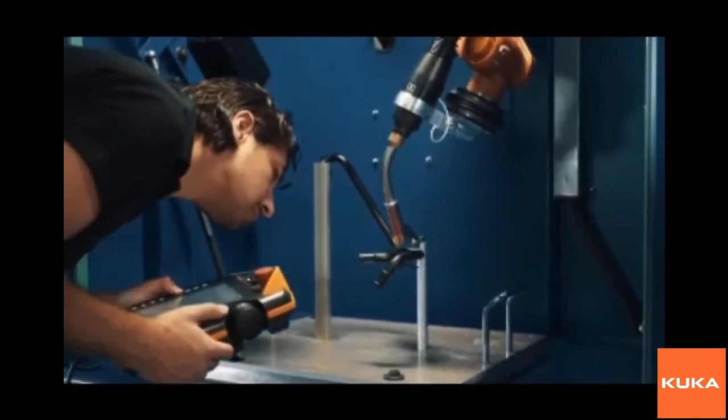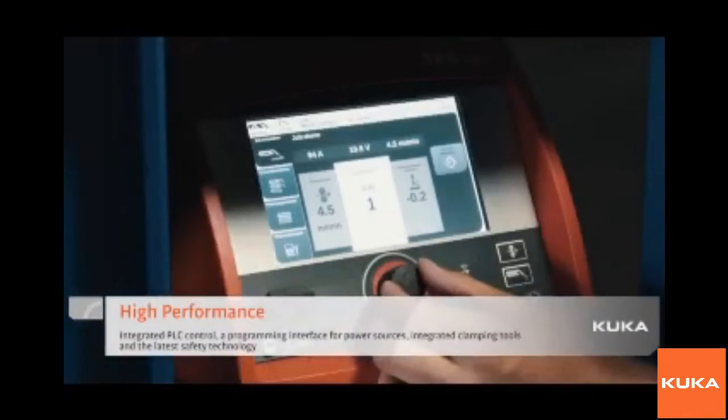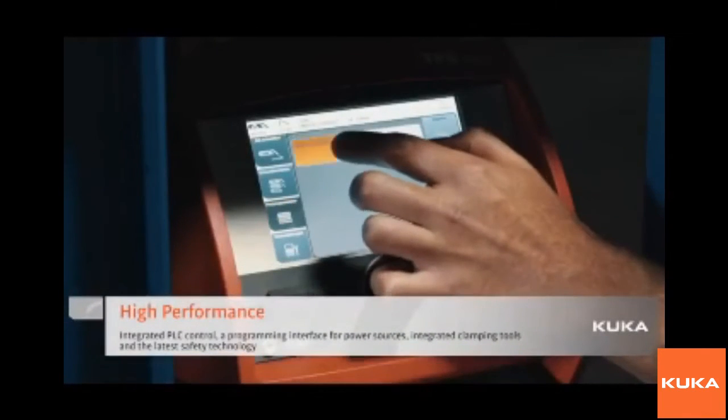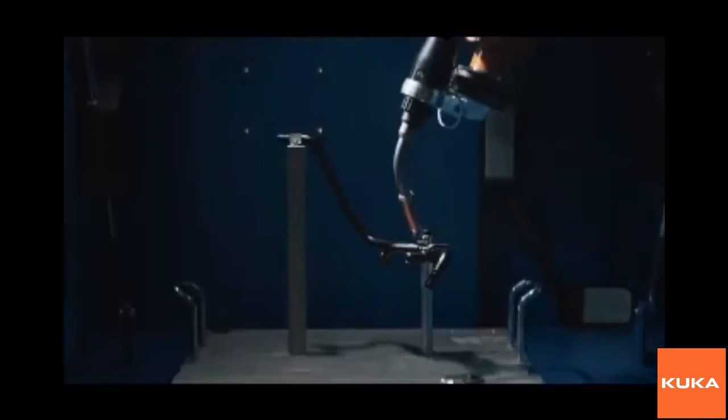You can see here the programmer is moving the robot. This is how he is teaching, and now you can see he is teaching with a 6-dimensional mouse. It is very easy for the operator to teach any program. Advanced programming is not required, no need to think about complexity. Here you can set current parameters and voltage parameters, and that's it. Once you start, the robot will perform a dry cycle, which means you check, and then it will start actual welding, and it will do it forever.